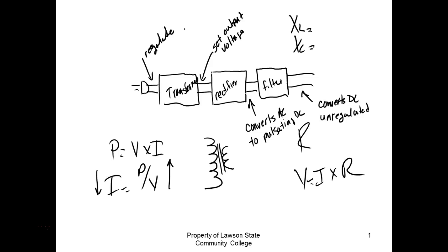So if I design something around 120 volts and then I go home and I only get 115, if I don't design around that range, then that's going to give us a problem, right? So even though my AC input varies and my output loads vary, our regulators are supposed to take care of that.